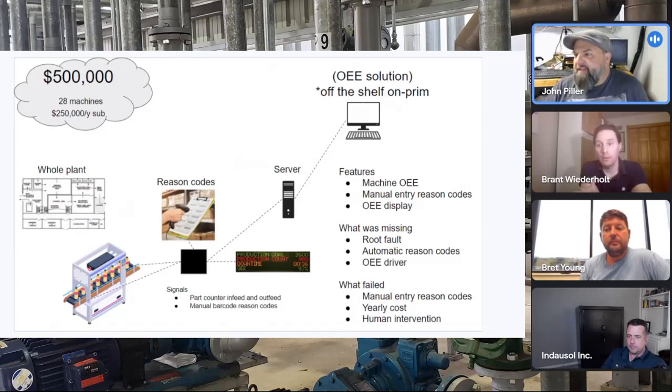So we had some of that data, but there was still data on the line that we had to collect, and we collected it with Raspberry Pis and pushed it up with Wi-Fi. And so each one of those Raspberry Pis was MQTT up into our cloud, and then we were OPCing and MQTT up to the cloud for the rest of the data, and then they were utilizing it. So it was like a dual path kind of solution.